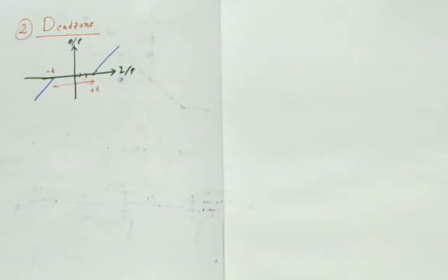Okay, and the valve is a motorized valve, which means that the motor rotates the shaft of the valve, and the valve is rotated but there is no flow of water. That means that you are applying input, but you are not getting the output. So this dead zone type of characteristic or nonlinearity may be present in the valve also.